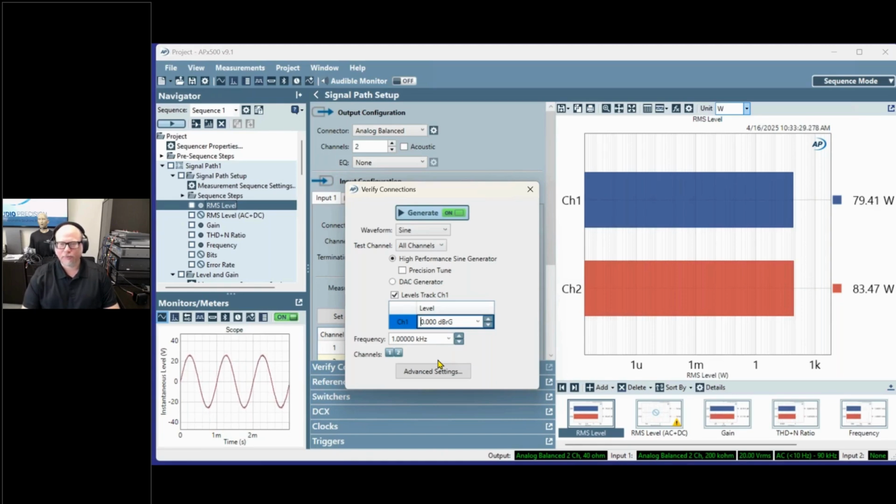It's a little bit of an old school definition, but exactly 1% distortion is classically defined as the maximum output level for an amplifier. Now, maybe you use 10%, maybe you use 0.1%, you can choose, but I'll use 1% for today.